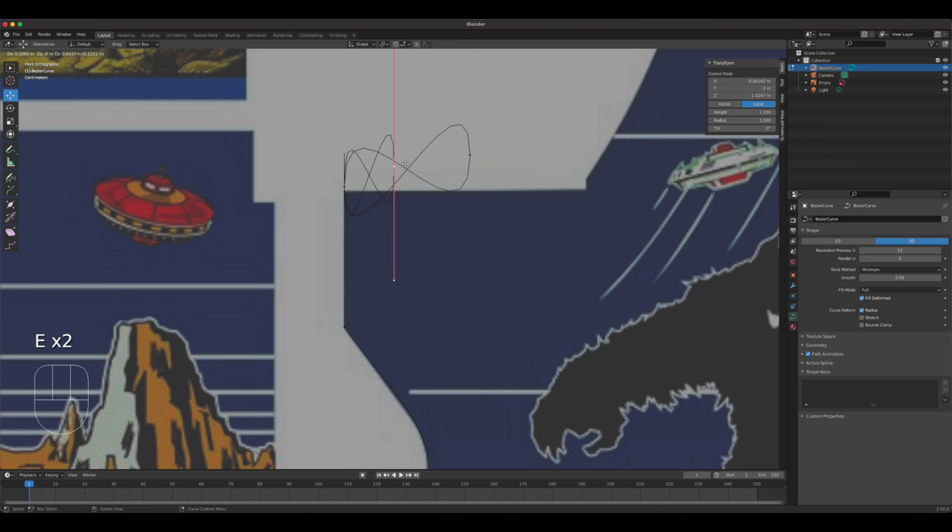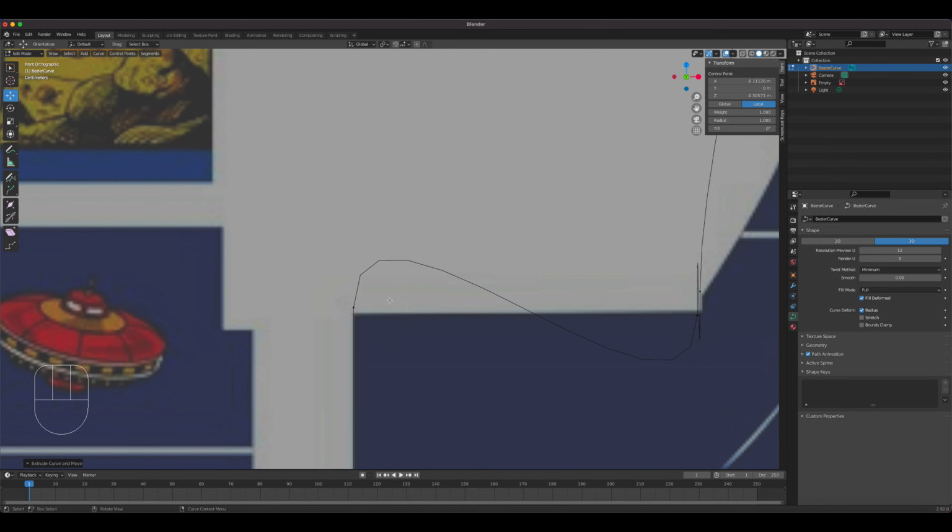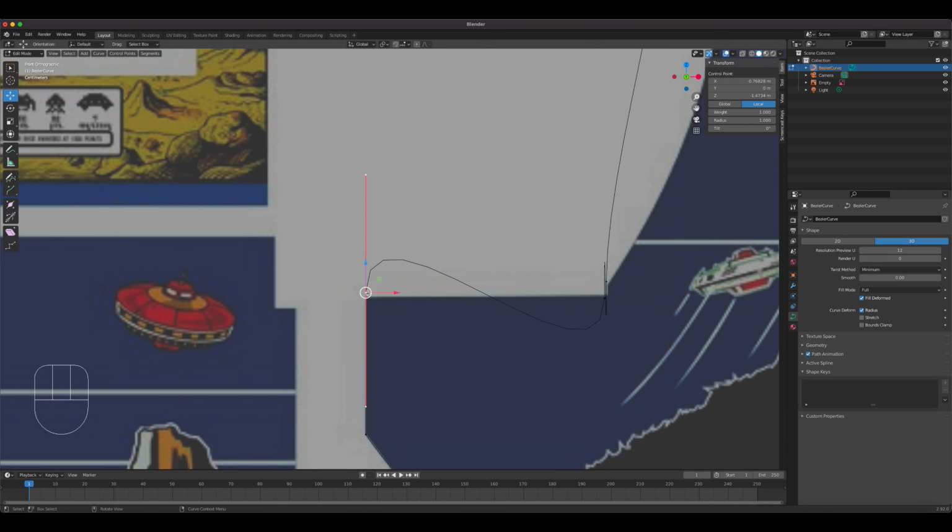All right, so instead of doing S0 and whatnot on this one, I would rather extrude this first. Oh, there's multiples in there. I don't know how many times. Okay, there we go. Press E. So I'm just extruding for each possible corner, okay? Now that I did that, I can just select this and S0. That one as well, S0. That one, no, that would be free, okay? Free right there, and then move that.